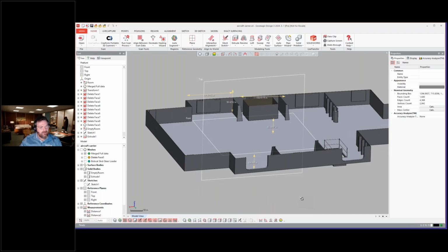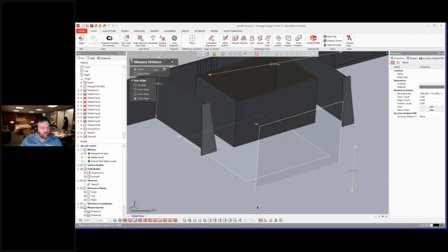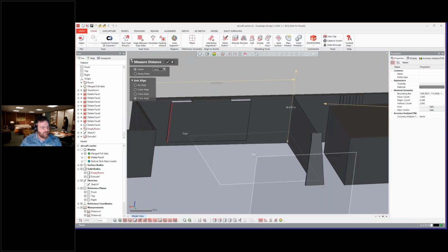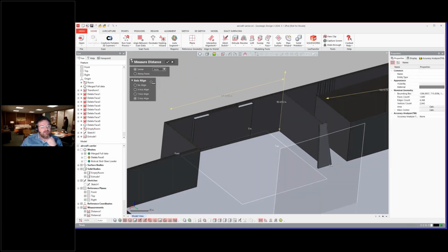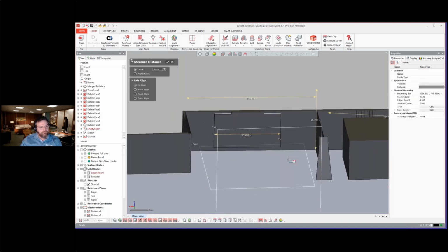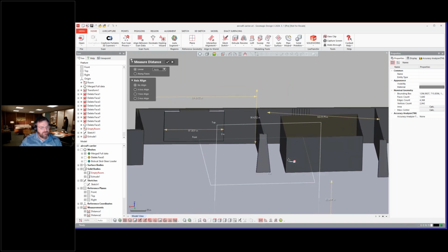we've created from that. And with the CAD, you can come in, and you can do this on the mesh as well. I'm just saying that I made these dimensions on there. So you can click on these different areas and create dimensions here. So if I wanted to say I want to create a dimension from here to there, create that line dimension. Oh, just turn off no align there, so I can actually create the dimension. So you can see here how you can walk around and pull dimensions from different things.